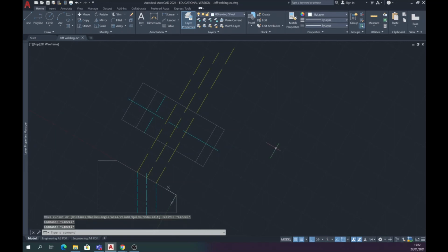So I'll do a further offset command. This time I'm going to make it 20. And I'm going to offset this center line, both sides. I'm going to perform a trim command, and I'm going to remove a little bit of the excess of those lines that I don't need. The rest can simply be picked up and deleted.